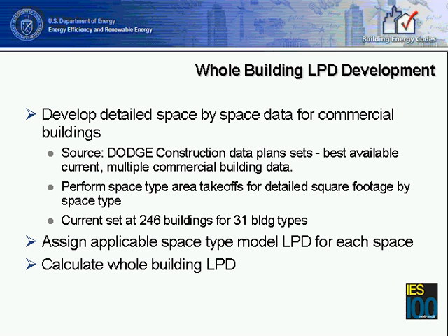What happens at this point is, with the space-by-space models, we now have to generate the whole building models if you're using the whole building compliance method. And instead of, as in previous standards where a whole building value was chosen based on consensus, these were developed using actual square footage data from currently constructed commercial buildings, real building data.